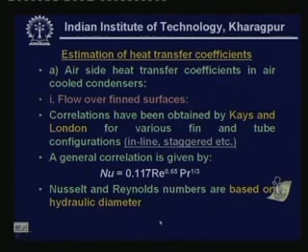So once you know the hydraulic diameter and velocities, etc., you can calculate the Reynolds number and Prandtl number. From that you can calculate the Nusselt number, and from the Nusselt number you can calculate the heat transfer coefficient.